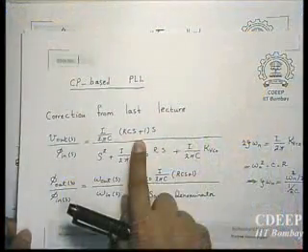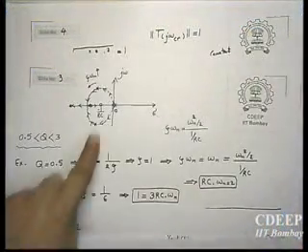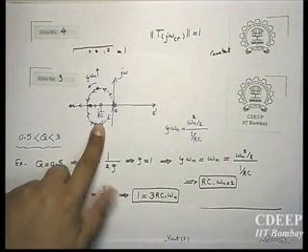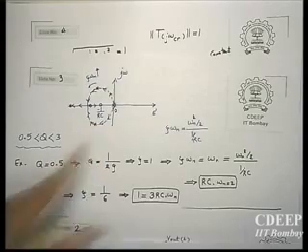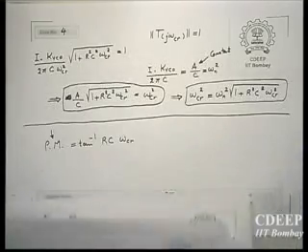If zeta is large, it doesn't mean that you don't have peaking. That peaking is because you have a 0. It's not because of Q. You may choose a larger zeta, like Q less than 0.5, but then you may still see that peaking. Then you don't think it is because of Q. You may wonder why it is like that. The reason is because your transfer function has a 0, and according to this root locus, your 0 appears first. Therefore, you will have some kind of peaking. So your transfer function may look like this.